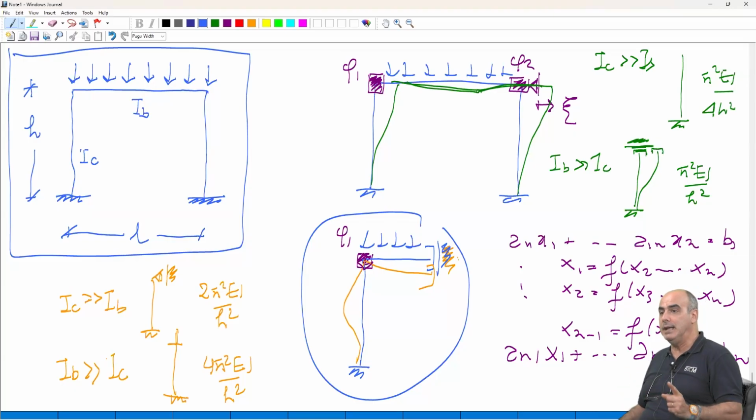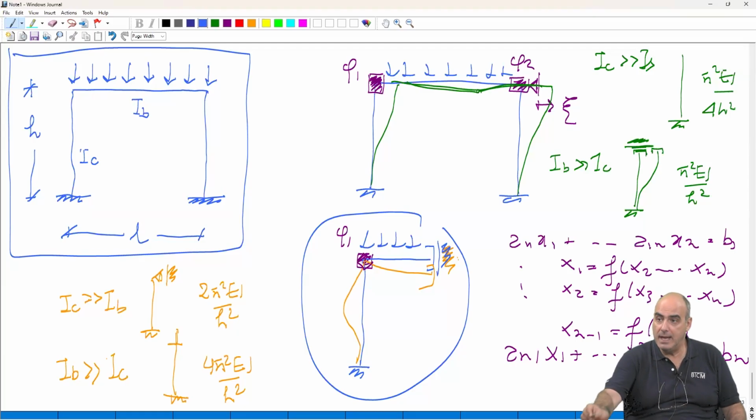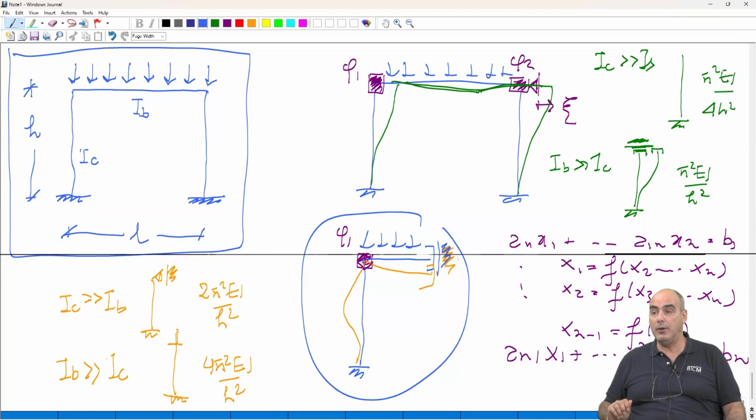Because the symmetry will introduce a spurious constraint, which, if you neglect the instability, is no problem because your stress state will not be affected. But if you have to check for instability, the fictitious constraint will prevent some deformation modes, and you will lose them. And you see, the error that you make can be huge because you can overestimate, so you are not in favor of safety. You will overestimate your critical load, your buckling load, by one order of magnitude.